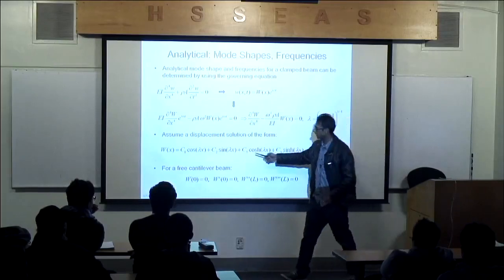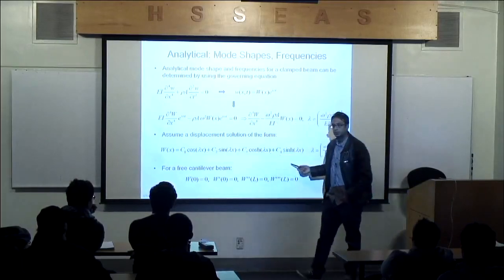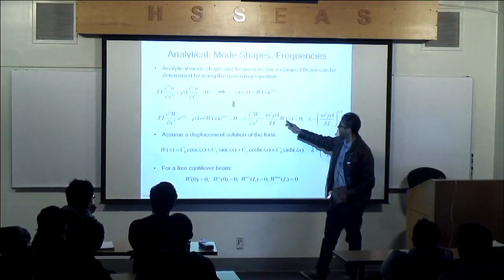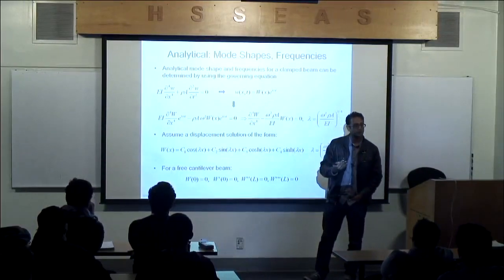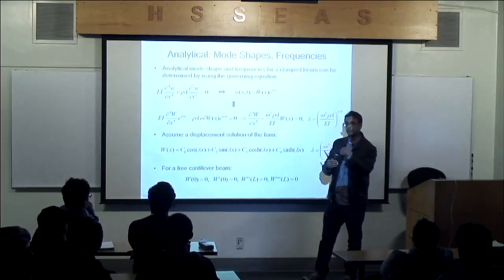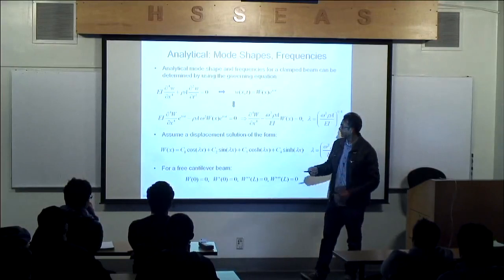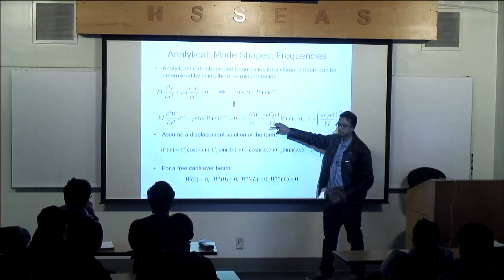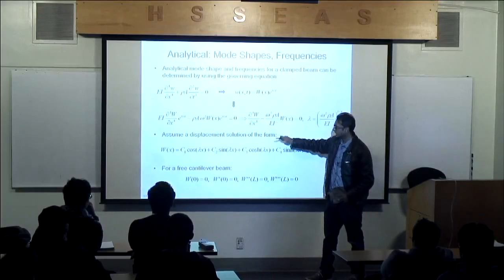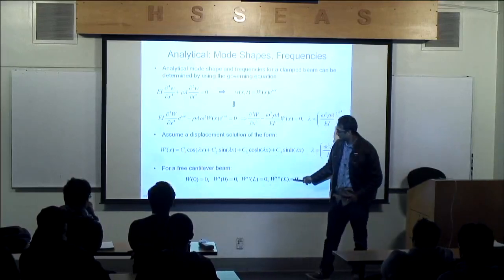You'll take a displacement of this particular form, and of course, nowadays you plug this into Mathematica or MATLAB and it'll tell you how to do it. But I think I need to remind you a little bit how this works, so when I go to finite elements, you understand a little bit better what we're talking about. So when I substitute this displacement assumption into this differential equation, and I enforce the boundary conditions of the problem.